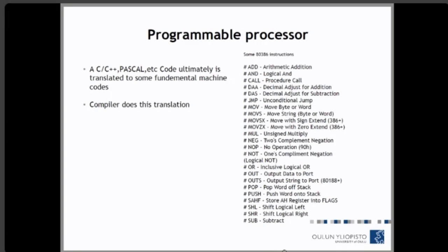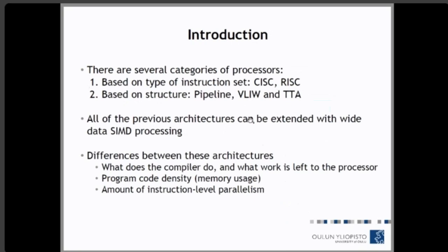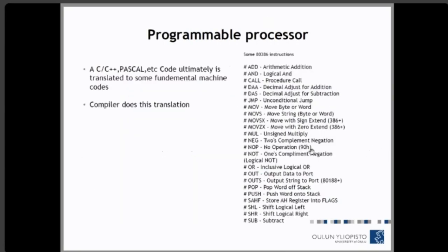But the idea was that if we implement everything in hardware, and since hardware is way faster than software, we will get higher performance. But then that idea later was challenged by the RISC idea. They understood that if you have some optimal number of instructions that can support any kind of software, you end up doing better in terms of performance and power, because most of the hardware that is supposedly there to accelerate the software is rarely used.